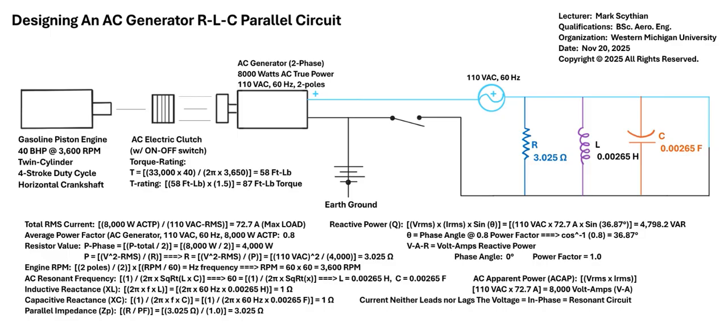And this is based on designing an AC RLC parallel circuit with a power factor of 1.0 so that the inductive reactance and capacitive reactance are equalized by implementing an AC resonant frequency design method, 1 over 2 pi times the square root of the inductance times the capacitance. So if we were to just isolate the L times C, or LC, to X, we could then solve for X and then find its square root to separate them into equal values.